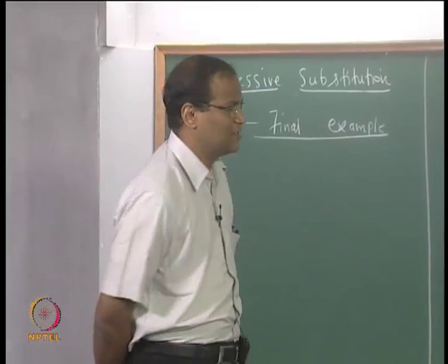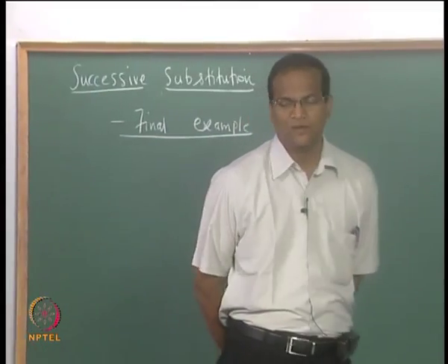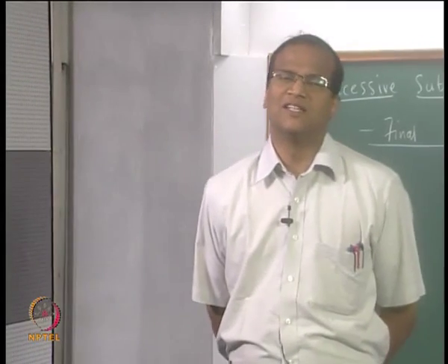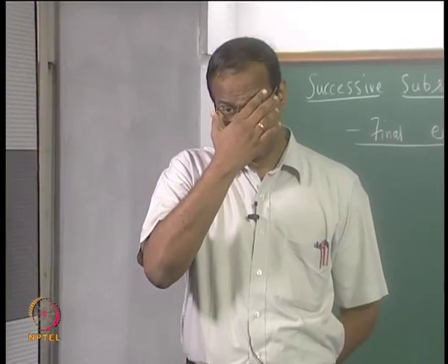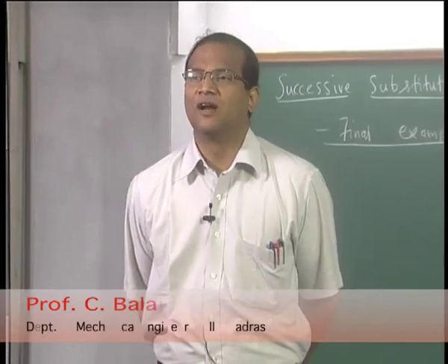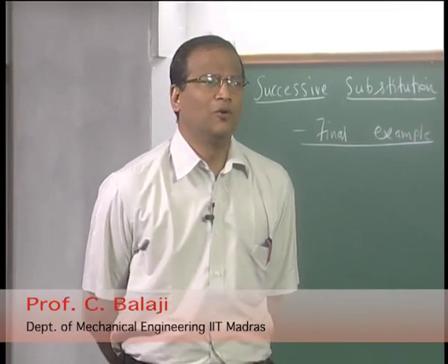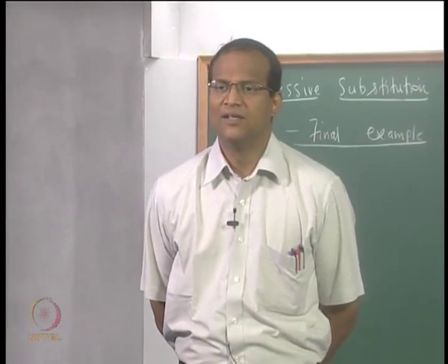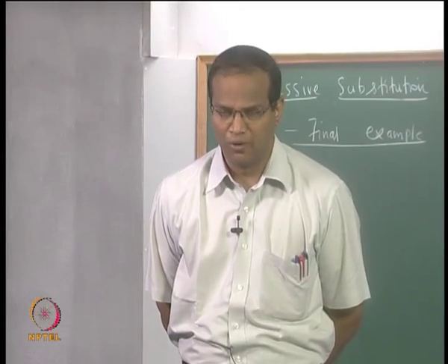Morning. So we will continue with our study of successive substitution. Today we will see one last example. This concerns the movement of a truck uphill. There are two characteristics involved. You have a load characteristic. You also have the engine characteristic. These two have to match, and you will get the operating point.